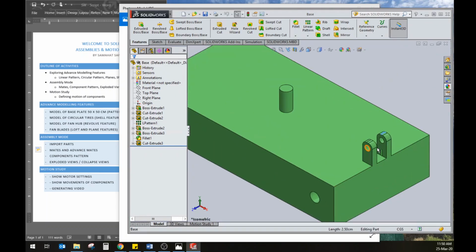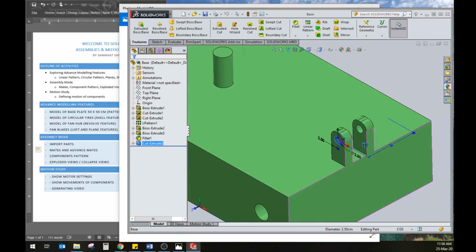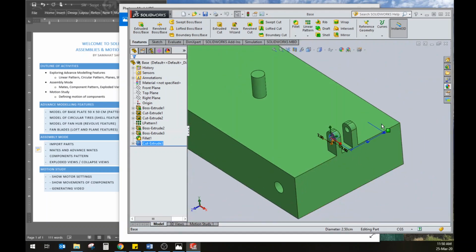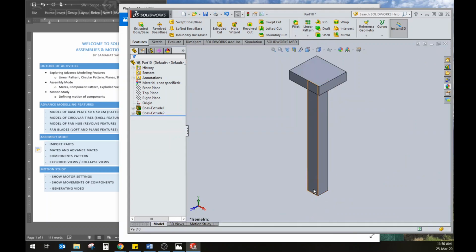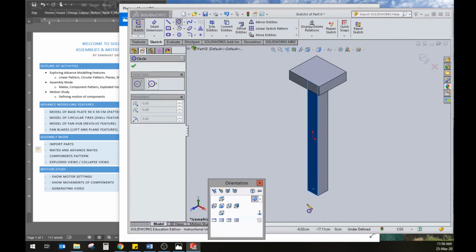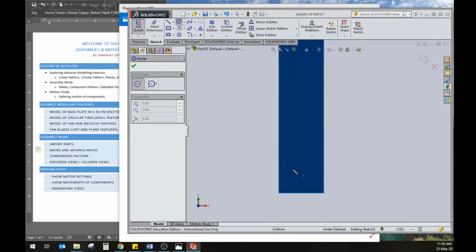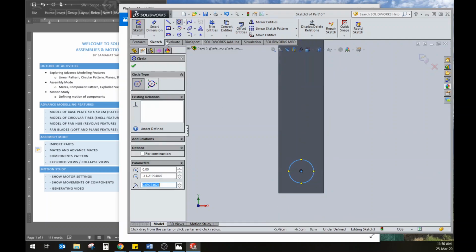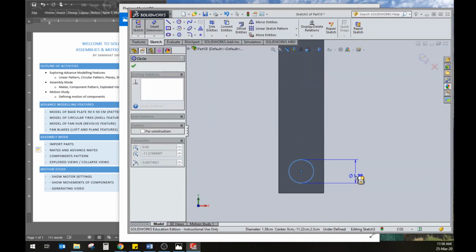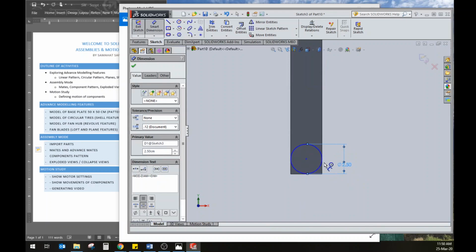So if I can go here and check what is the size of this hole, it was 2.5 centimeter. And I can make my hole 2.5 centimeter in the arm. So I'll just close this one, go back to my arm and click on this edge, click on sketch and click on circle, and then make my view normal to this face, and then I'll just make a hole roughly in the center of this around dimension of 2.5. Okay, did you see the issue?